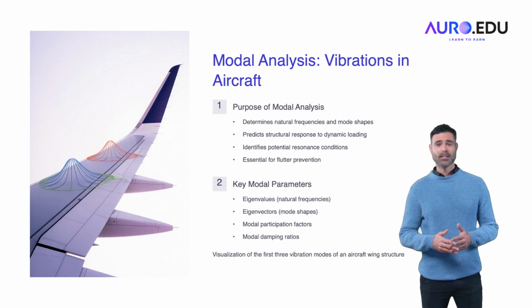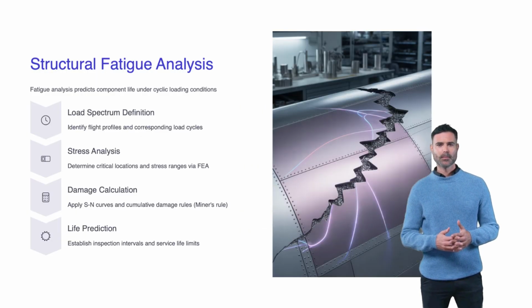Identifying potential resonance conditions is essential for preventing flutter, a potentially catastrophic aeroelastic phenomenon that can occur at certain vibration frequencies. Modal analysis is crucial for preventing structural damage due to dynamic forces, ensuring the structural integrity of wings, fuselage, and other critical components. Visualizing the first few vibration modes allows engineers to identify weak spots in the design and improve its dynamic performance. Fatigue analysis and safety margins.